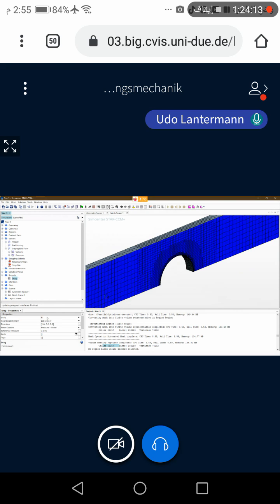So unit Newton is fine, laboratory is also fine, direction is, it should be drag, so the x direction is fine, 100 means x direction. Pressure and shear, in this case it's fine, we don't have shear in this case because it's inviscid, but in the next exercise it will change to laminar and therefore shear will be included.